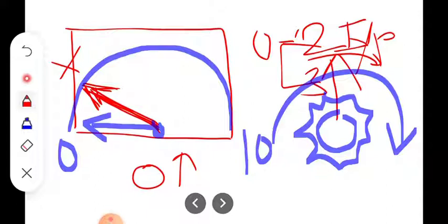Is it understood? Means initially in case of the threshold, from 0 we are increasing the input, the pointer will not show deflection up to a certain or minimum value of input, and that minimum value of input is nothing but the threshold. And what is the resolution? From 0 we are increasing the input and the instrument starts the deflection, or the pointer starts the deflection from 0 itself. For the increase in the input, the instrument starts showing the deflection of the pointer from 0 itself. But after reaching a certain input, the pointer will not show any deflection for further increase in the input, and that value is nothing but the resolution.